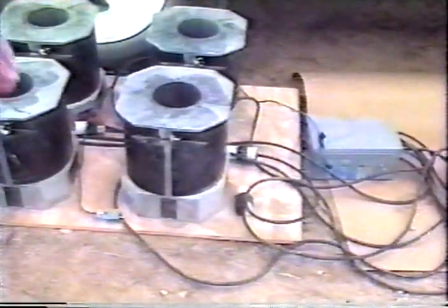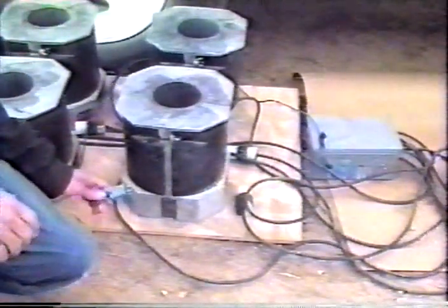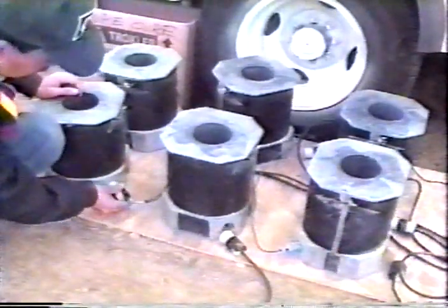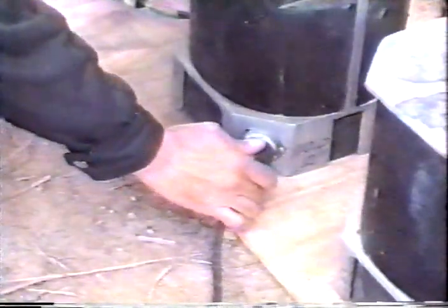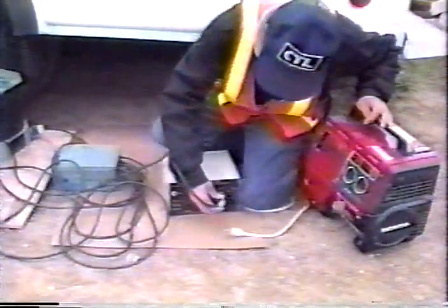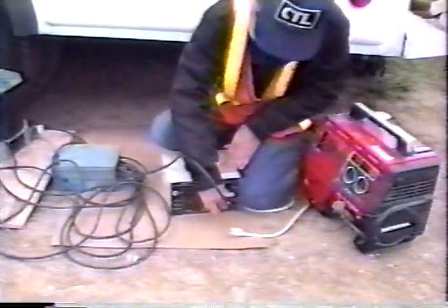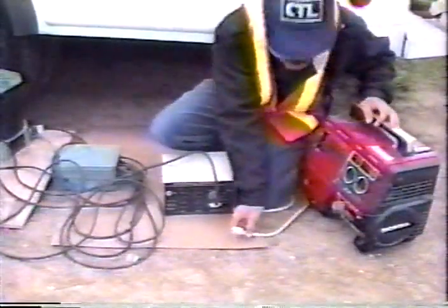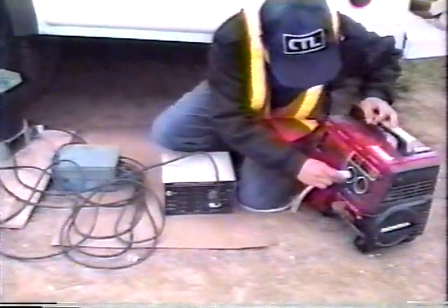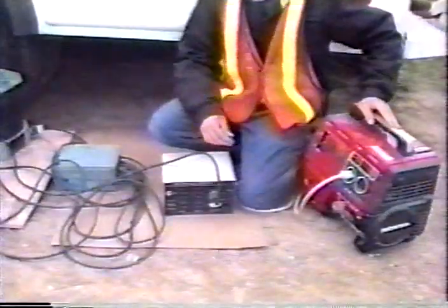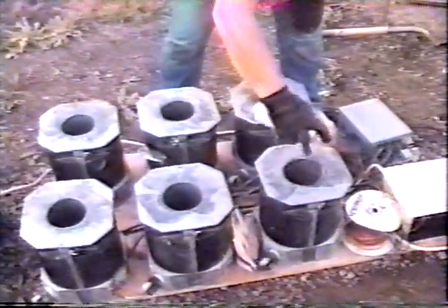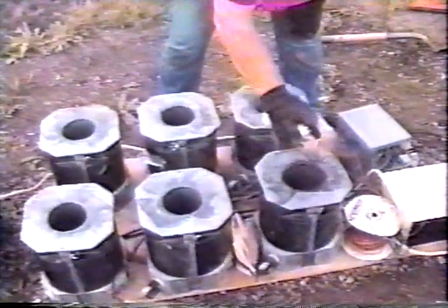In setting up the system and getting it started, the thermocouple wire coming out of the controller is first plugged into any of the molds. All the molds are plugged into the cables coming out of the controller. Then the controller is connected to the power supply through the stabilizer. All connections must be securely made to the right places. Also, each mold must be sprayed with form oil.